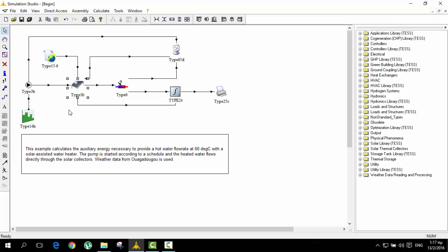So what we do is implement the black box model. We measure the input, we measure the output, and then we try to fix the model to fit this input and this output. So this is what a black box model is: you have the input, you have the output, and you have to try to build what is in between in a very simple way, so it can run fast, it's efficient, and it's very easy to understand.